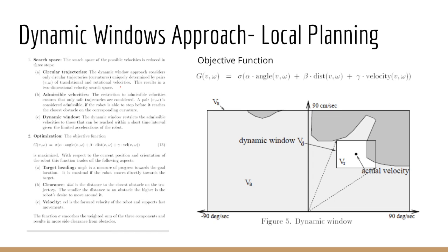The planner gives us a rotational and translational velocity, which we can use to move our vehicle. So essentially, our approach to local planning with the DWA is to find the desired motion and the direction, give steering commands, and then take into account the limitations on acceleration. Again, this is done by maximizing the objective function and producing rotational and translational velocities, which look like segments of circles, and those are easy to check for collisions with the obstacles.